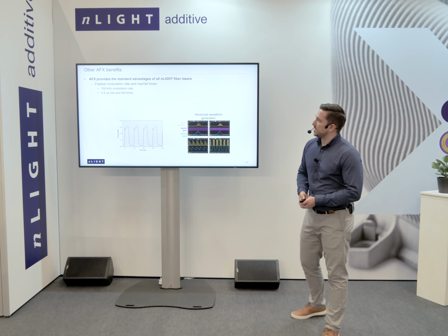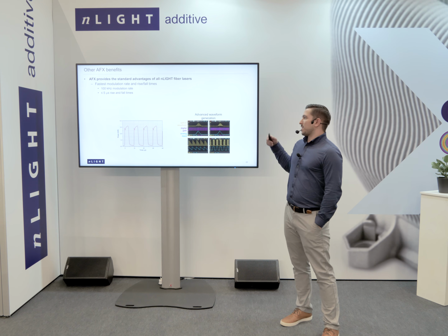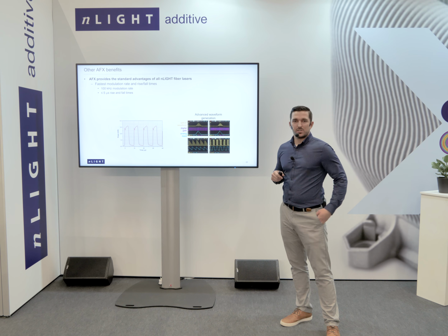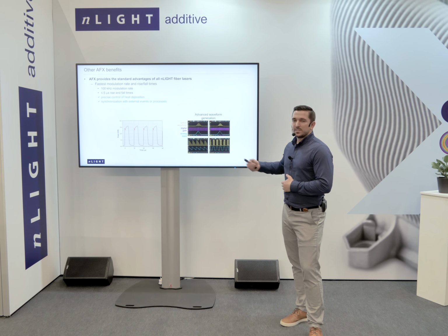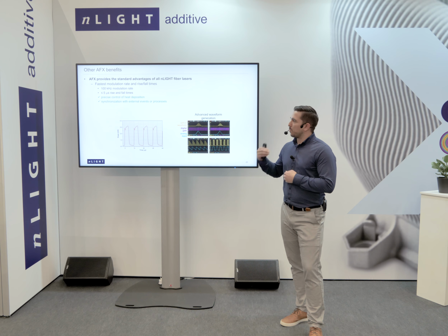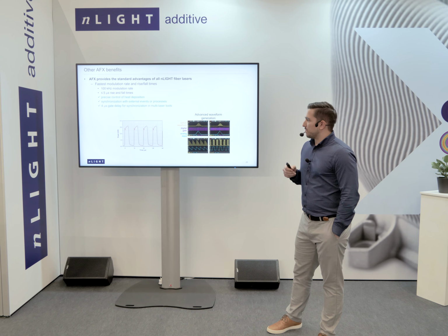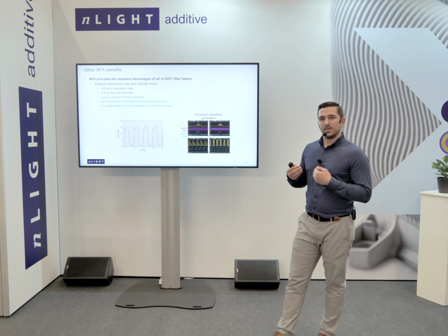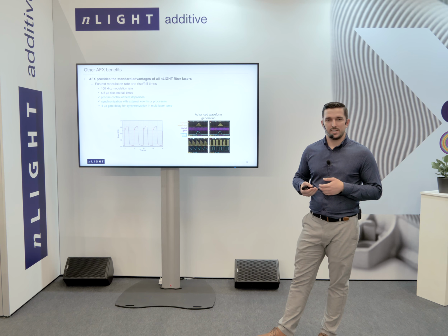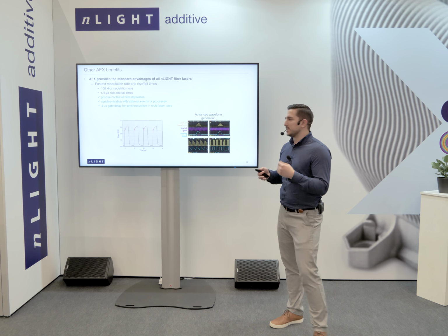One other feature is we have the fastest modulation rate and rise and fall times in the industry. So that means you can modulate your laser at 100 kilohertz with rise and fall times of 5 microseconds. This is particularly useful. You can apply power where you want it, when you want it, and our electronics are also very fast in their communication. So if you have a multi-laser tool, the gate delays from laser to laser are very consistent and will be less than 4 microseconds. You don't have to worry about lasers emitting unsynchronously.